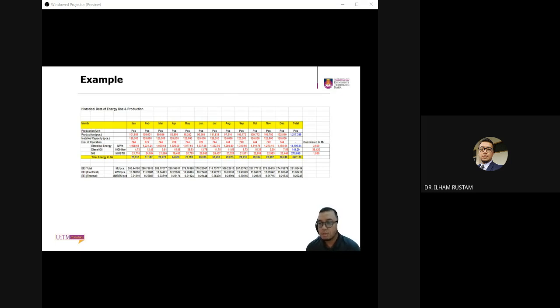You need to have this kind of data across. It can be years, it can be months like this, depending on what you want to try to achieve. So here you can see this is the output, the production being produced, and this is the energy unit that you need to divide over. So here 1000 divided over 101 production, you'll be able to get the EEI, right? So double check on that, because EEI here shows 265.